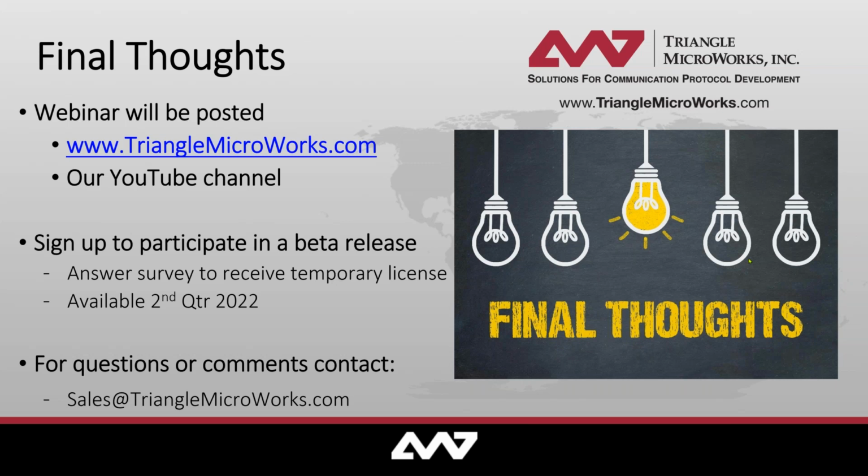However, we can also build these actions to do higher level functions. For example, interlocking is a common one that is very time consuming to test. You have to basically go through every breaker in a system and make sure that the conditions are set up, and then the breaker will not operate if the interlocking conditions aren't met, and it will operate if they are, or vice versa. I get that backwards. Anyway, the point being is all that done.